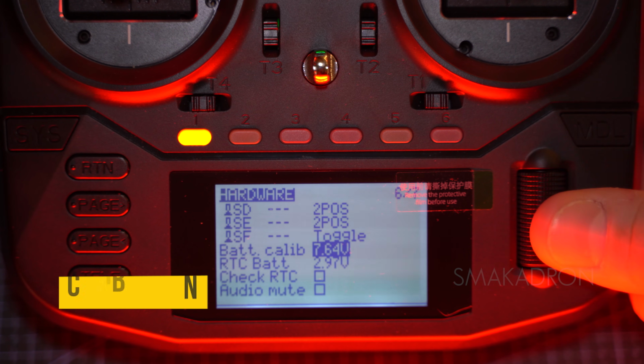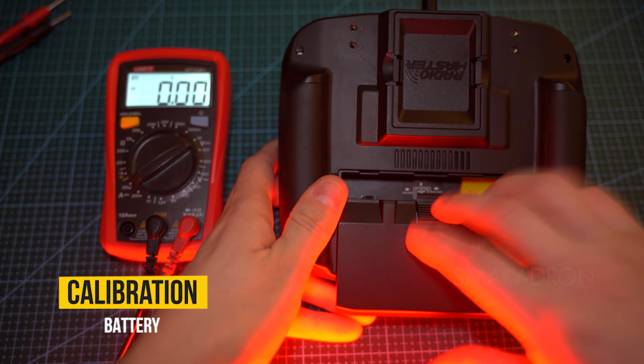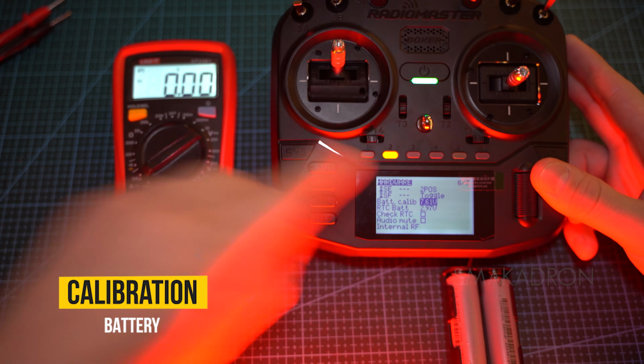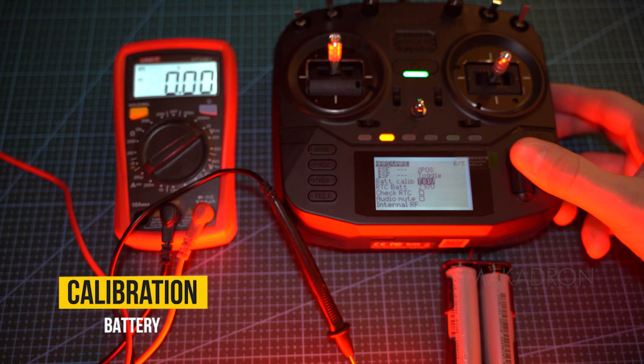Battery calibration. For the radio to show accurate voltage values on the main screen, you need to measure the battery voltage with a multimeter and enter that value here. The decimal values will be hard to set because the selection roller's step is too large, but I set it slightly higher than what the multimeter shows.